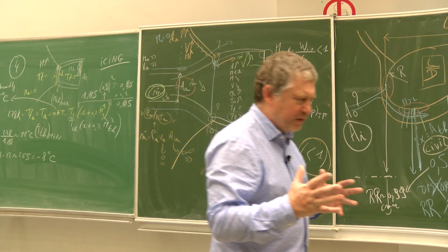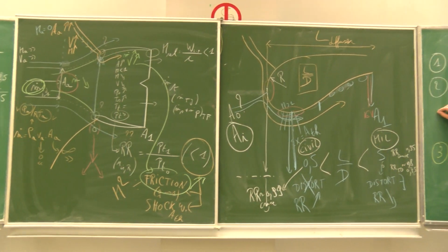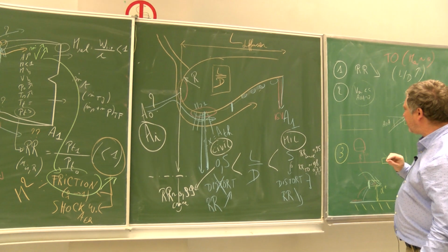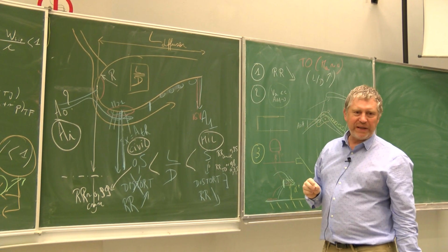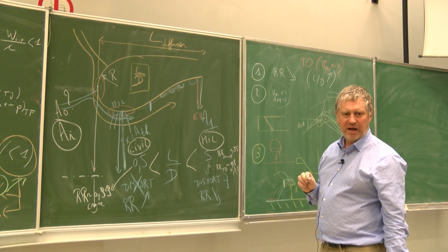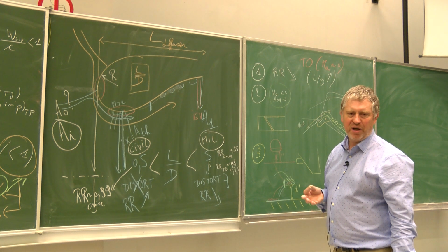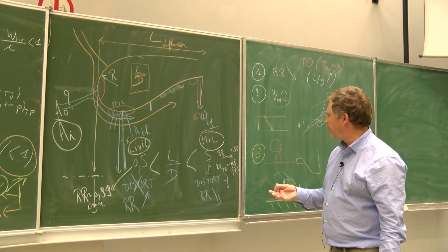Also, and this will be the final example I will give, in the intake, let's say you have an intake like this, you can also have a grid that is lowered down like this, if you have a danger of stones, branches, or bad conditions on the runway.